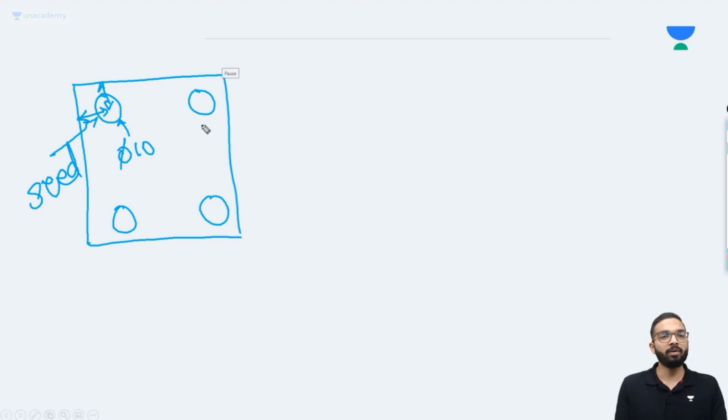Now what I will do is that I will pattern this hole. There are different ways of creating this same geometry. What I can do first is that I will pattern this hole in this direction and then get these two, the first one and the second one, and then pattern these 2 holes together in this direction to create these 2 holes at the bottom part. This was the first way.